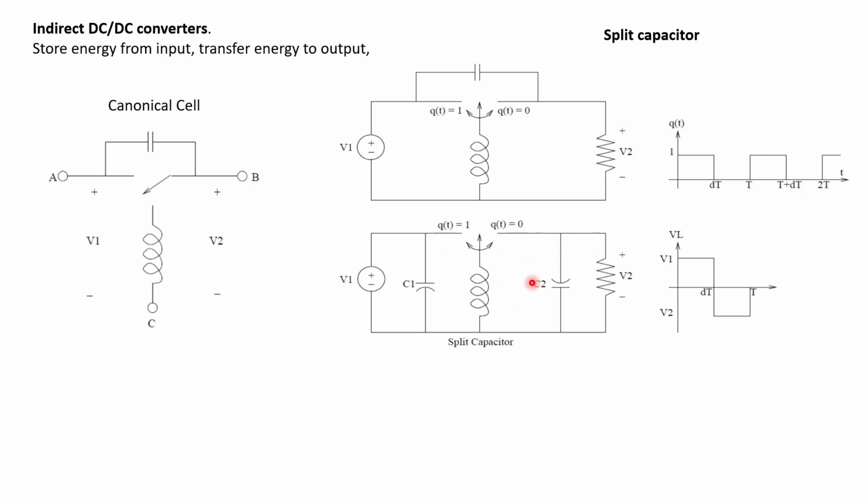So from here you have the voltage VL, the voltage of the inductor, equal to minus the voltage V2. Why minus? Because of the way the current flows. When you switch here, you charge energy like this. So this one spins the magnetic flux, for example, this way.